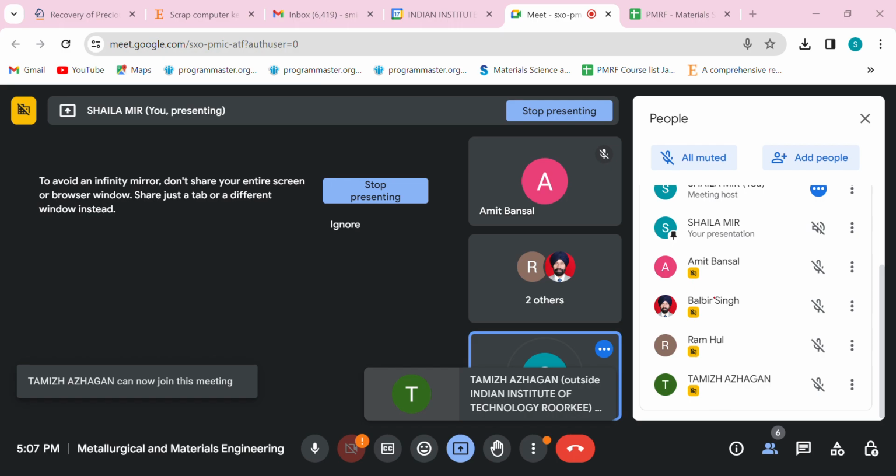Otherwise, you can also have a combination where these fibers are in the transverse direction, and there the same formula will not be applicable. That will be a different case. But here the tensile force is acting along the fiber axis. So we can apply the rule of mixtures here. You are given the modulus of your aluminium, and the modulus of your fiber is given.